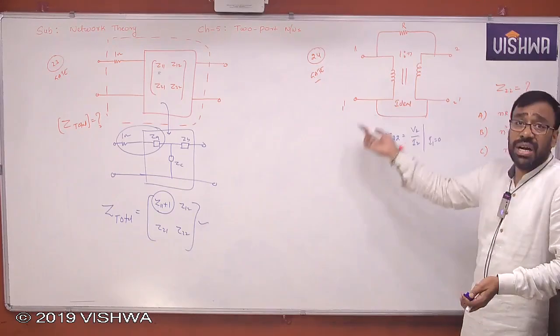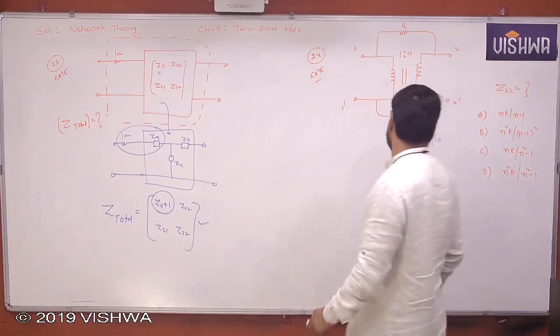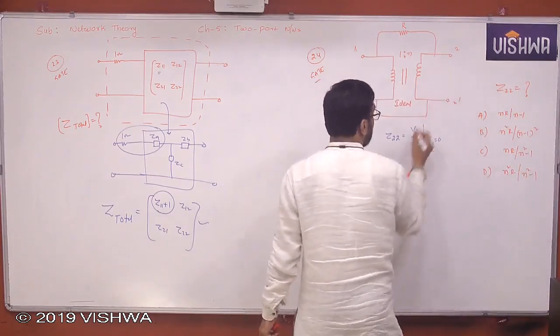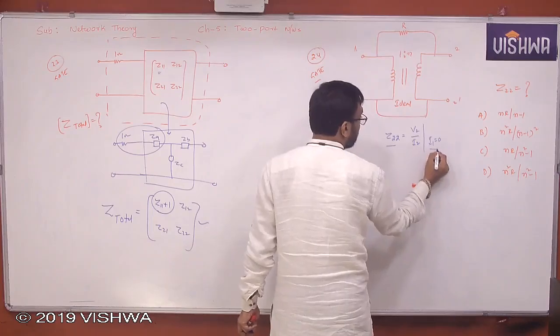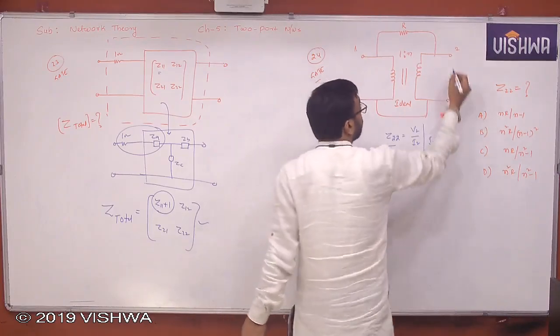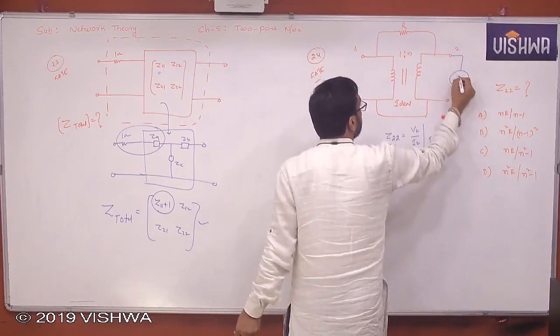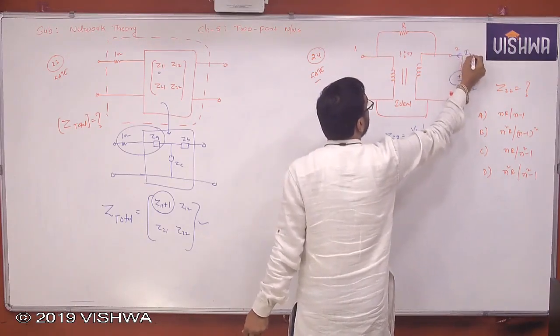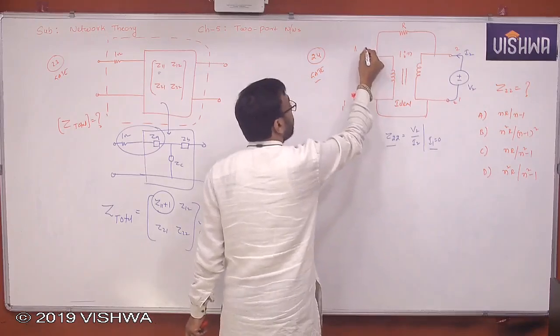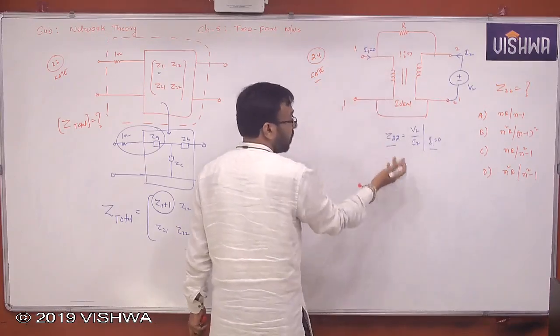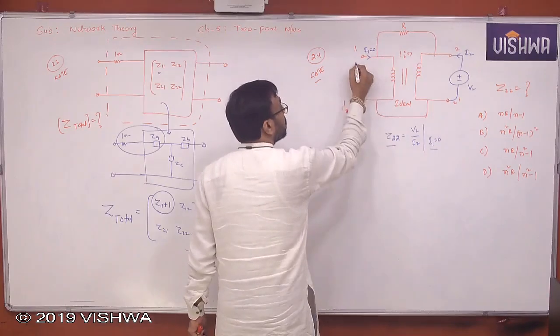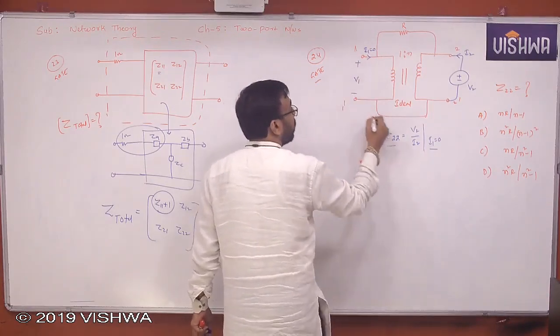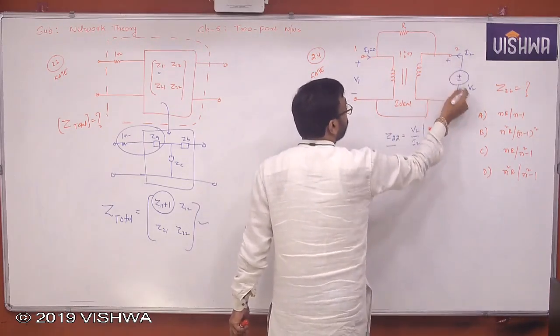Let me apply the same conditions here. So, okay. So, let me connect. This is nothing but output impedance under the condition I1 equal to 0. Okay. So, let me connect. This is plus minus V2 and here I am injecting I2. This I1 is made 0. Otherwise, I can't define what is Z22. This voltage is V1, I can define, and this voltage, I already know, is V2.